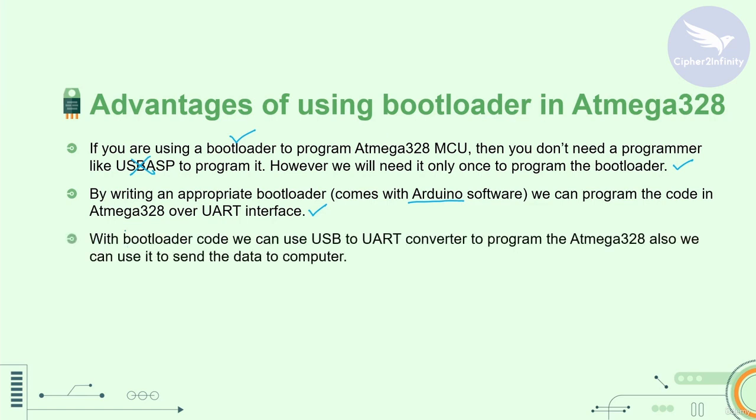With bootloader code, we can use a USB to UART converter to program the Atmega328. Also, we can use the same hardware to send data to the computer. So I hope you now got the advantage of using the bootloader code in the microcontroller.